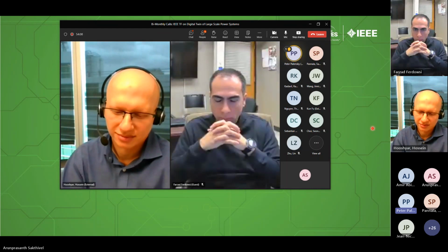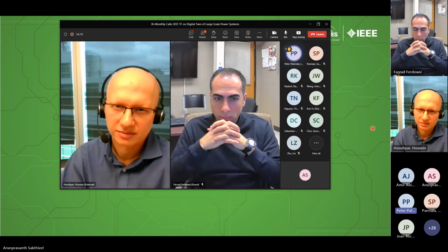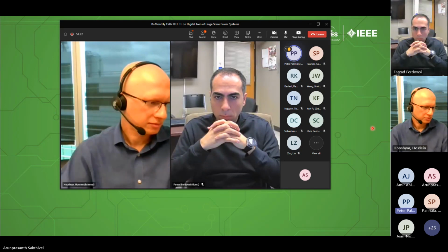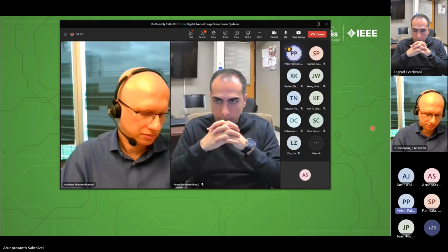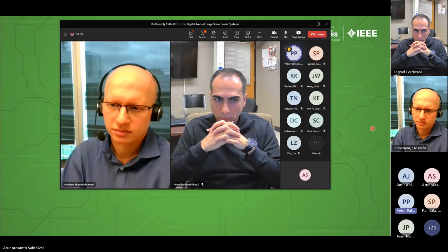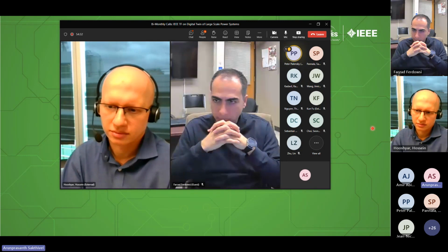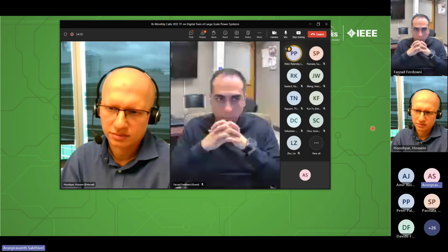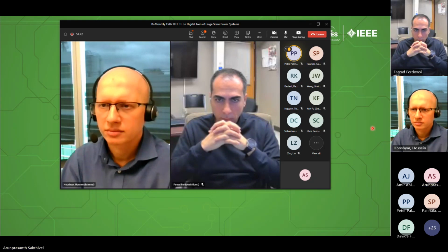As far as I understood your case, you get the EMS data, update the files, compile it, and run something like your protection relay sanity check. Then when the next update comes, I don't know what the time step is, but probably an hour or 20 minutes, you do the next case. Is that correct? That is correct, Professor. The EMS data comes every hour, and we try to do a list of contingencies within that hour and produce the results for each snapshot.